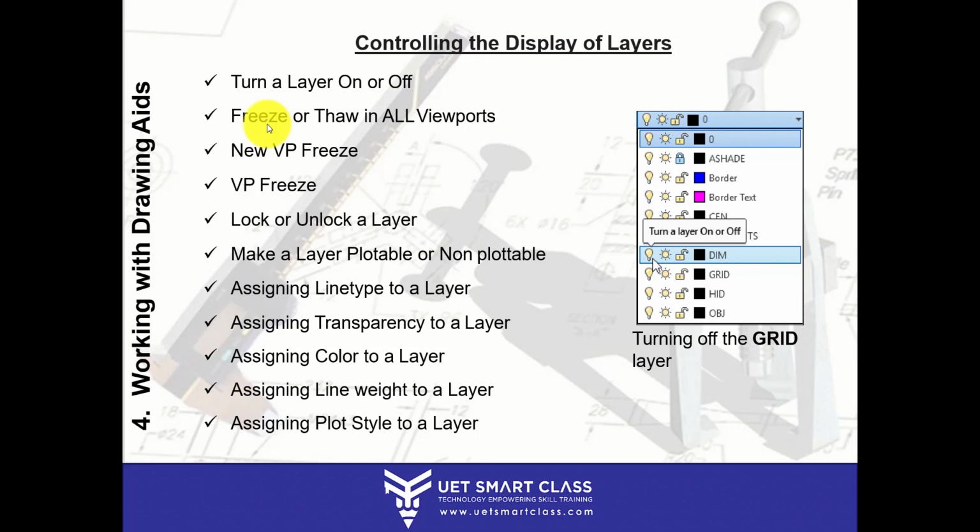The space it is taking in your AutoCAD system or in your computer system, it will decrease the size of the file. You can try that. You will learn it in the coming sessions. One more important point is that when you have frozen layers, whenever you open a new session, AutoCAD regenerates every time, and it will take less time because it will not regenerate those layers which are frozen. All right, because the file becomes heavy.